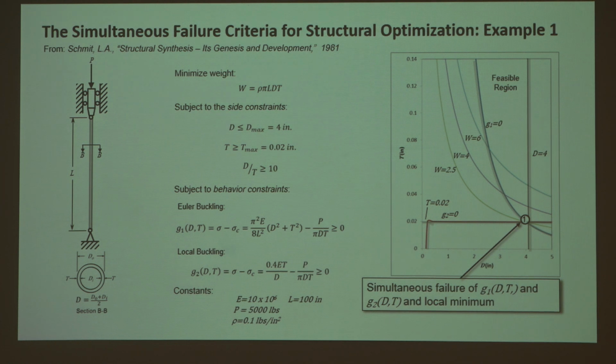And we've got two constraints here, G1 and G2. They are equal to the difference between those two stress levels. If that difference goes to 0, that means we failed. We hit the point where it fails. Understand? So therefore, the region of interest is where those constraints are greater than 0. Okay? And we're going to take those constraints, G1 and G2.